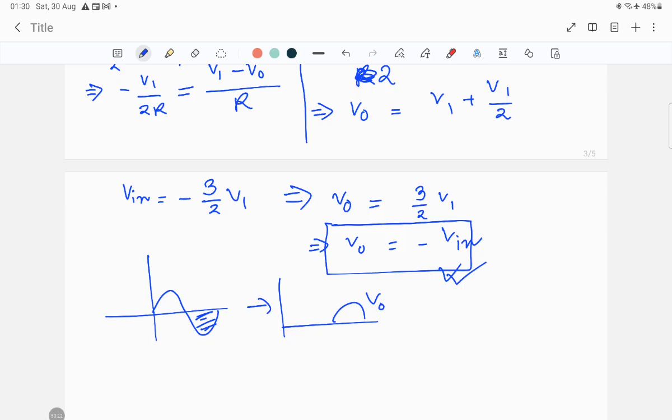Okay, so suppose you are asked, whenever you are working with a very low amplitude signal, with a very low input signal, definitely without looking for any other orientations or configurations, just simply go for the precision rectifier. One catch is that the input signal must be lower than the threshold voltage of a diode.